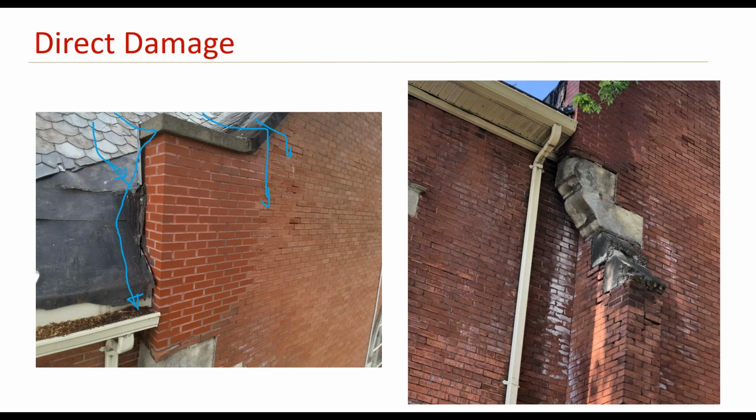Now water would flow, and instead of going to the rain gutter directly, it would actually seep through these penetrations and overflow over the brick veneer. And of course, the same thing would happen here. Instead of being conveyed away from the building, it would just overflow and again get absorbed by the brick veneer. The problem with the water being absorbed by the brick veneer is, now we get the moisture absorbed in when it's raining or when the snow is melting.